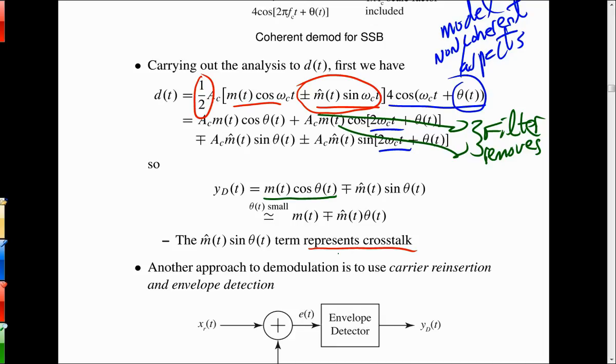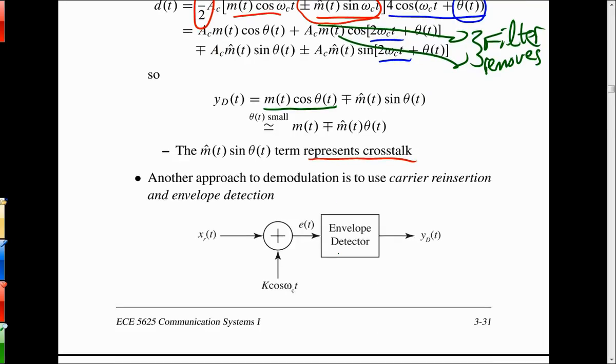Don't you still have that overt signal in there that you don't want? You have it in there, but make that term much less than 1, and then it's just squashed down. Squashed down on a dB scale, I guess, is the way I'd think of it, because decibels is popular terminology. If we can squash it down to be 60, 70, 80 dB down, we won't notice it. If it's only down 20 dB, it's not that noticeable in speech.